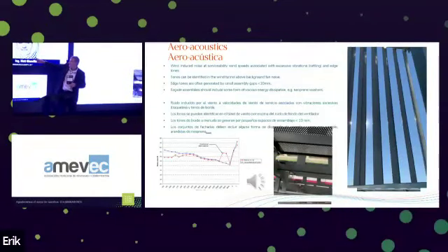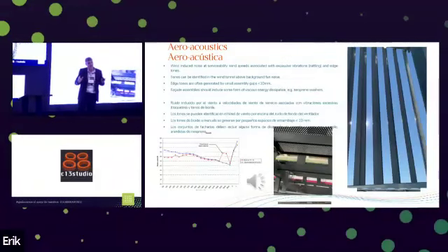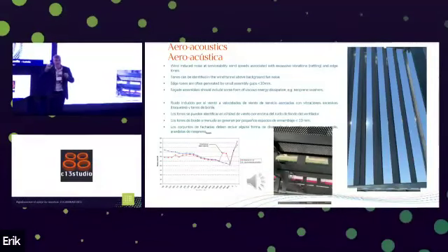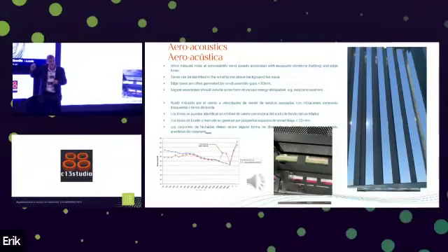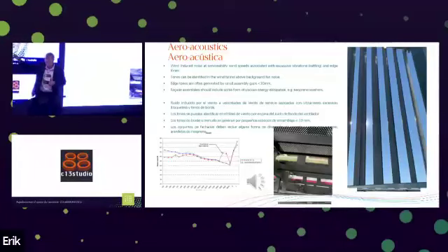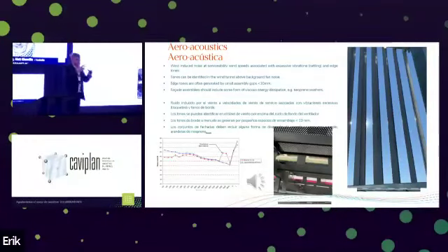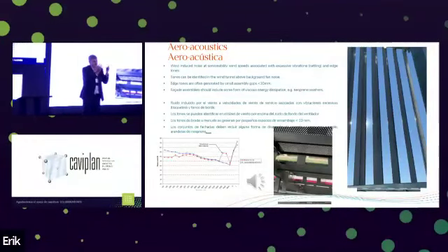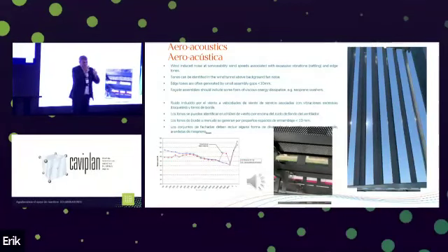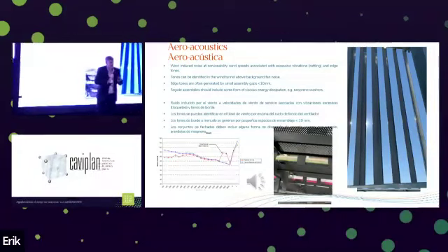If we get larger holes, let's just say greater than 20 millimeters, then this is far less likely to occur as we've found in the field. So make sure there's big gaps, if there has to be a gap, like in the screen, and avoid small gaps, not just in screens, but in your assemblies. So in your facade assemblies, don't have little gaps between your mullions and transoms. Make sure everything is hard flush against each other.